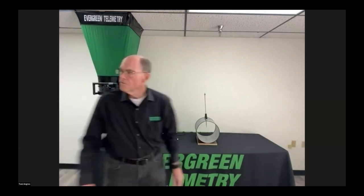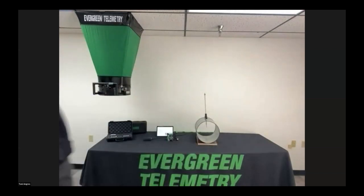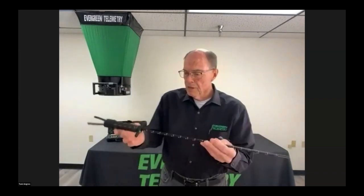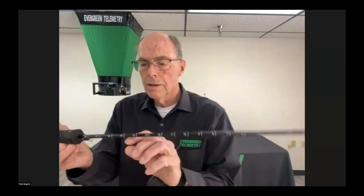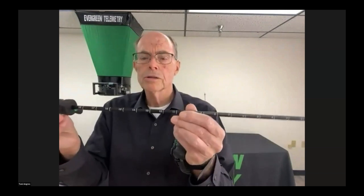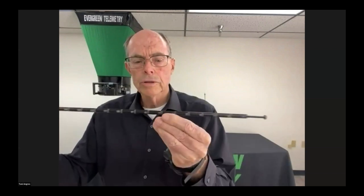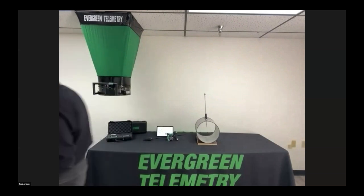Do you want to speak, Pete, to the notches in the airfoil? Thank you. Tony reminded me to point out that first of all, the inch marks are very easy to see, and they're notched so that as you are doing a traverse, you get a little tactile feedback from the edge of the duct interacting with the notch. Thanks, Tony.